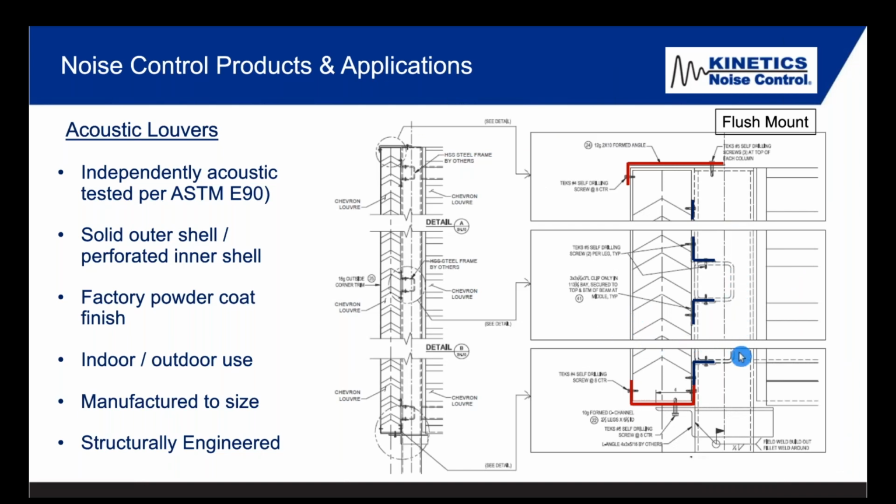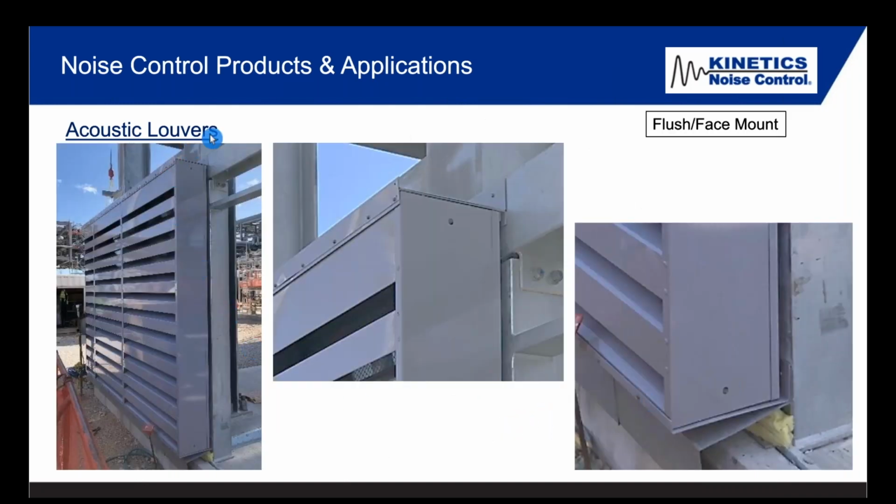Mounting louvers to third-party steel instead of the barrier wall system, you can mount louvers to that. And there's different options, this is an example here. You see the steel behind it. You see this top system, and I actually put that in there so you can see it better. And then the bottom attachment here is a continuous channel, and that's all engineered to be the proper gauge, the proper structural strength to meet the local IBC wind, pullouts, and uplift.